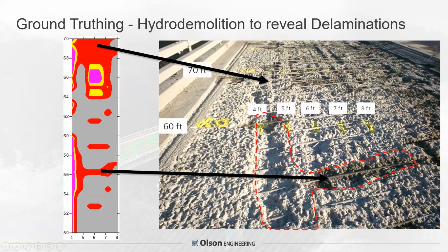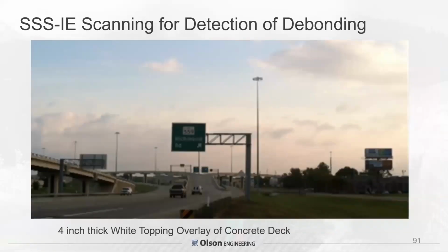So there's good correlation. We've gone on to test over 30 decks with asphalt overlays for Colorado DOT and others, using a combination of impact echo and surface waves combined with radar.